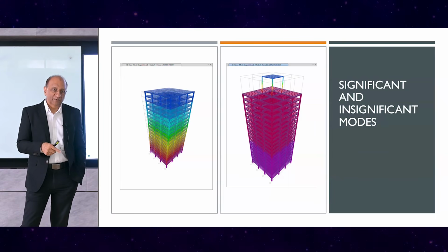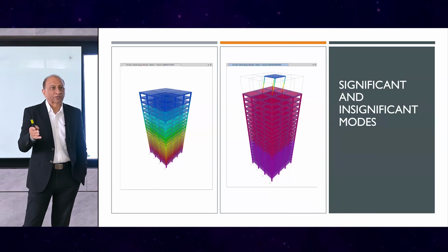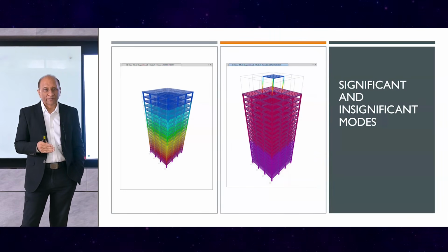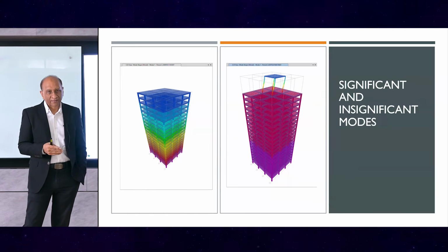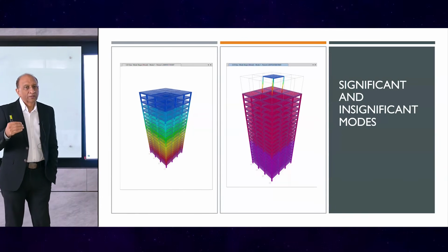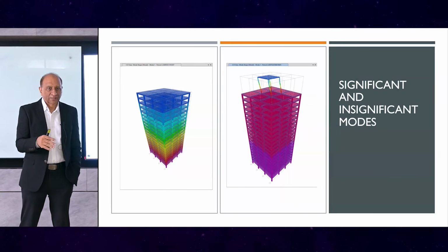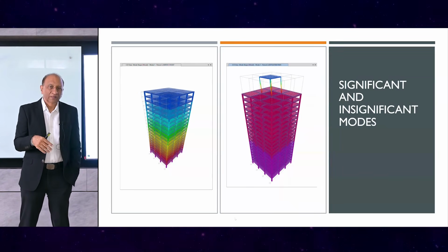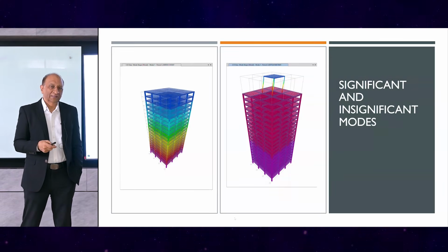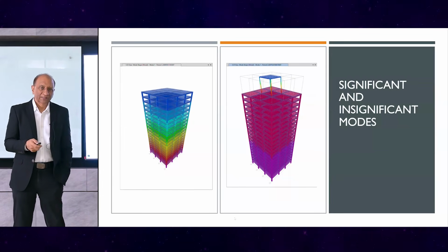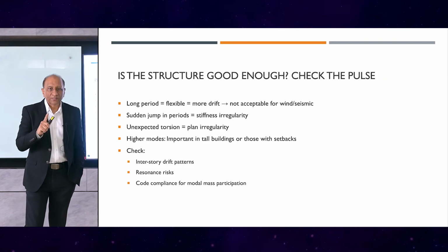And if you're doing pushover analysis, for example, and if you by default select the first mode, then it won't be right, because the first mode on the right-hand side will only select the top canopy and not the structure. And the target displacements and everything will be incorrect. So we have to be careful to see that the modes are global for the global response. For local response, we could look at those separately. So for a case like this, probably it's unnecessary to model the canopy in this global structural system, and we can just apply it as loads.